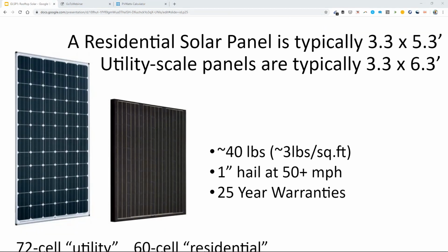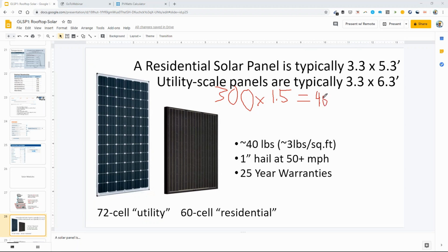So coming back to the program, if I'm doing a 300 watt panel and I'm producing 1.5 kilowatt hours per watt per year, I'm producing 450 kilowatt hours per year out of this panel. And this panel is, I'm just going to call it 20 square feet, even though it's less than that. And so we're looking at a little over 20, about 22 kilowatt hours per square foot